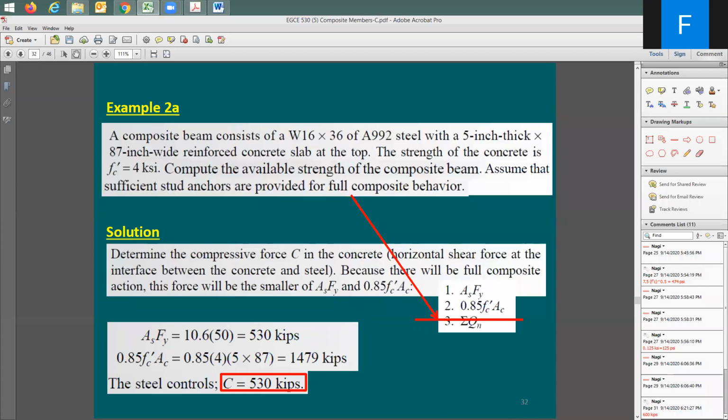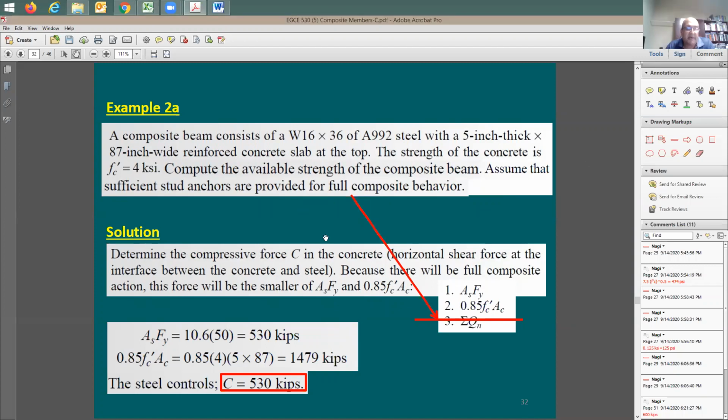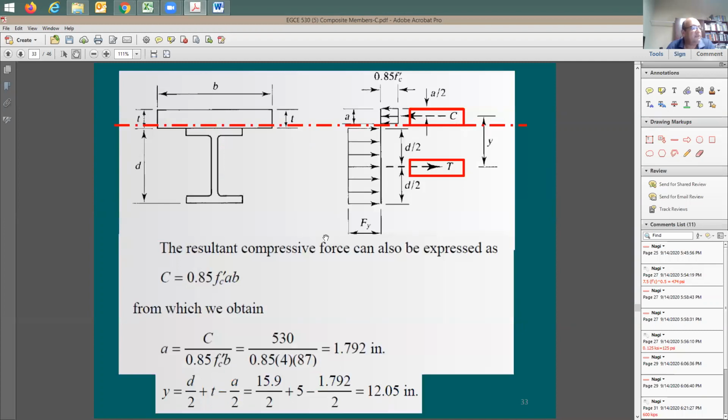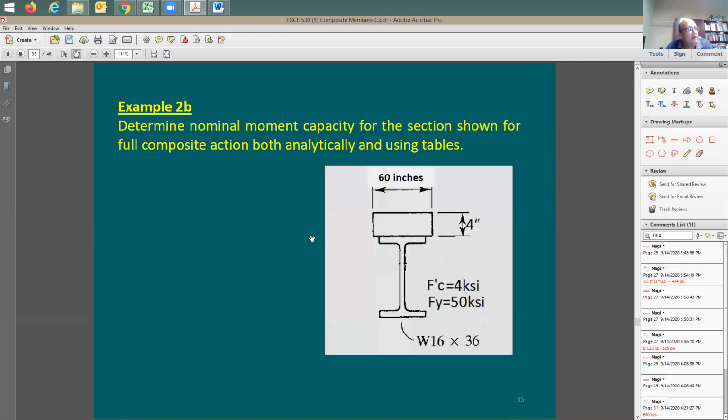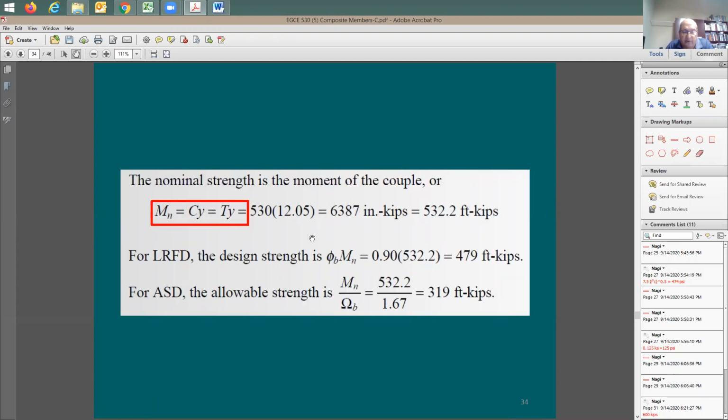Okay. So if the beam is fully braced on the top, you're going to end up here with 240 kip-foot. If you do it here with LRFD, you have it at 479, and you have 100% additional flexural strength. I guess it's worth being used, right? You cannot really ignore it. This is a lot. Any questions before I move further?